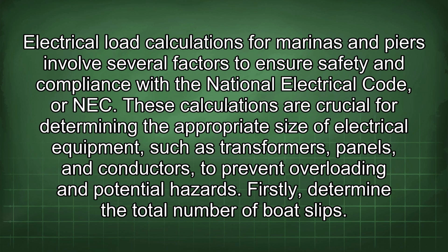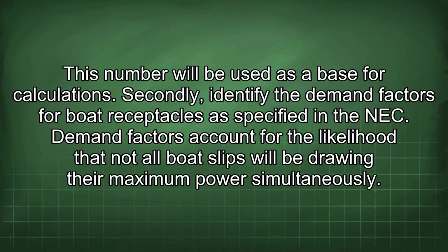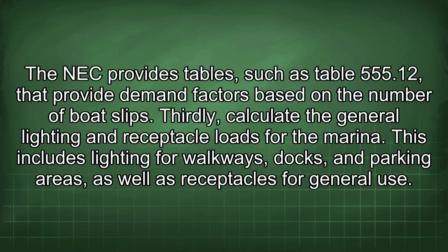Firstly, determine the total number of boat slips. This number will be used as a base for calculations. Secondly, identify the demand factors for boat receptacles as specified in the NEC. Demand factors account for the likelihood that not all boat slips will be drawing their maximum power simultaneously. The NEC provides tables, such as Table 555.12, that provide demand factors based on the number of boat slips.